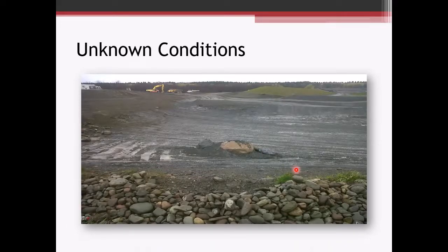There's always a certain amount of risk associated with geotechnical work. We don't have X-ray vision to see everything that's below the surface, so we're typically taking soil borings or samples at discrete locations. And I use this in a lot of my geotechnical presentations to emphasize the variability of subsurface conditions. So if we really needed to take one soil boring at a site and we happen to take it right at the spot where we would hit that big boulder there, we may conclude that we have shallow rock at the site.